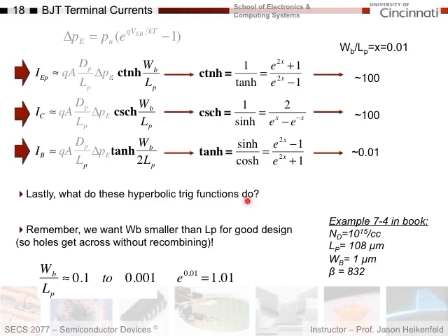Well, they are basically what differentiates between the magnitudes of the emitter current, the collector current, and the base current. I know with the BJT that if I have amplification, the emitter and collector currents are much greater than the base current, and that's exactly what these functions do. Essentially, they give you the ratios that lead to amplification factor.